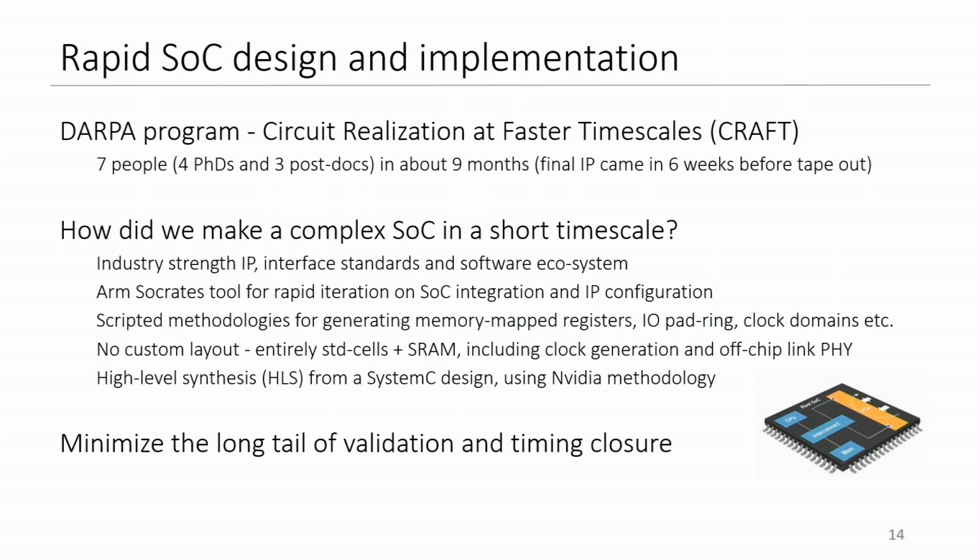We used only standard cells and SRAMs, and that includes things like clock generation and off-chip link PHYs, which is usually done with custom layout. I think that saves a significant amount of time in terms of DRC and LVS and that kind of thing. Finally, again, under the CRAFT program, we used high-level synthesis to design our Datapath accelerators. And we actually used a methodology that Nvidia Research developed, who were on the same project, for that.